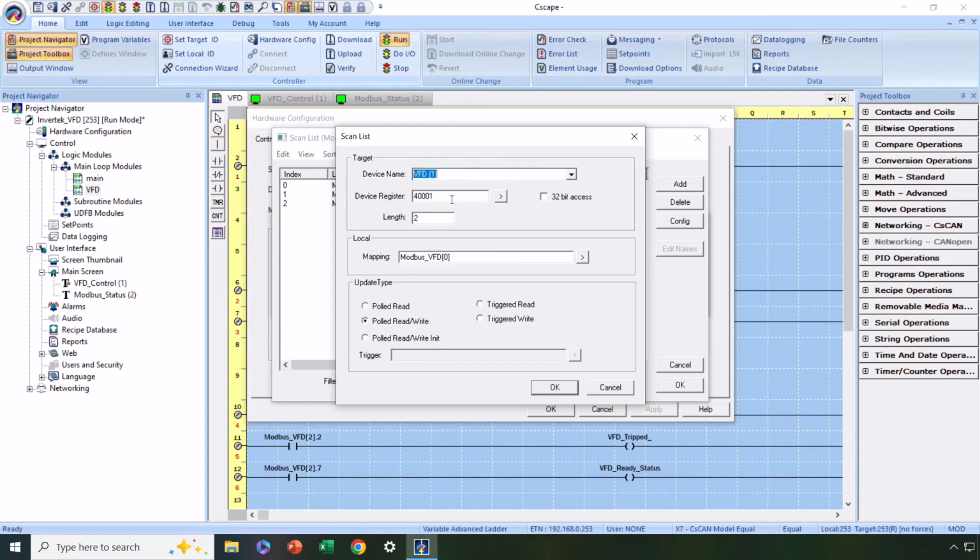All of our Modbus data with the drive will be mapped into this word type variable because we are only using holding registers with the Invertech drive, and holding registers are always word type variables. We have created a long word type array where we can put all the Modbus data that is going to be read and or written. Then in our OCS program, this is where we will find the holding register data to either read or write.